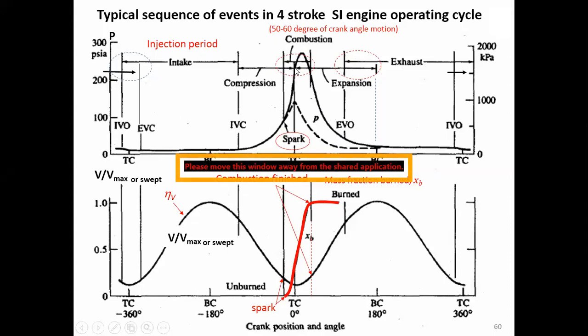Right? And then when the piston starts to move down from the top dead center, the expansion stroke happens. Okay. So the piston starts moving down and down and down, expansion happens. Right? The exhaust valve starts to open here. At the point where the exhaust valve opens, the exhaust stroke happens. Right? So you see a portion of overlap between the expansion stroke and the exhaust stroke right here because of the exhaust valve opening.